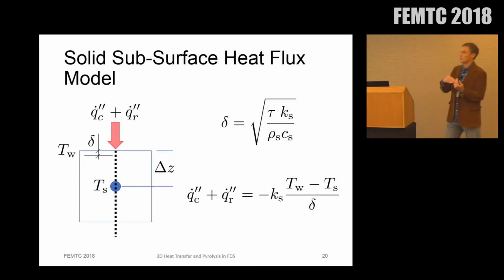I'll point out that the previous verification test was only testing mass conservation, so the actual result is not an analytical result for the 1D model either. But doing something like this reminds me a bit of the way we treat stresses and heat transfer in the gas phase, right? We're not resolving the viscous sublayer in the gas phase either. So we have some kind of a submodel, in this case internal to the solid, to get the correct thermal flux without explicitly resolving the gradients there, which would obviously be prohibitively expensive.